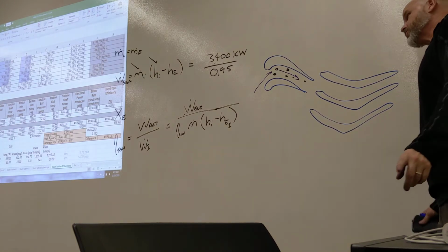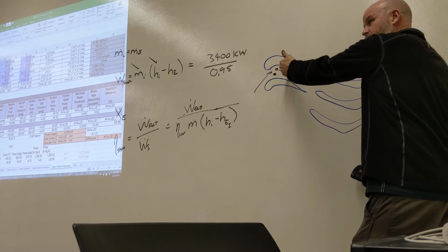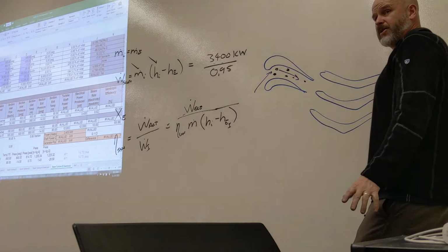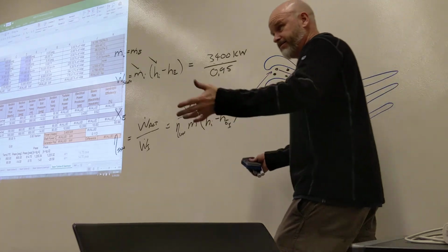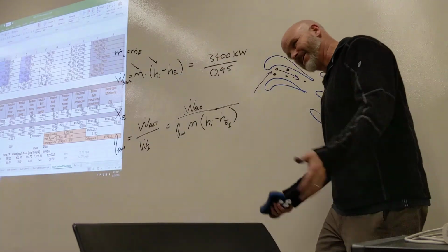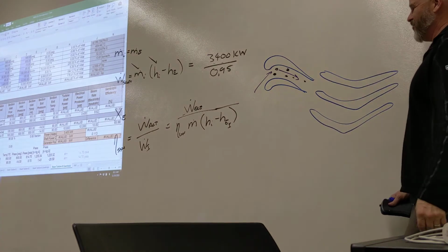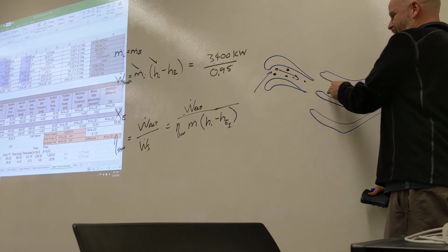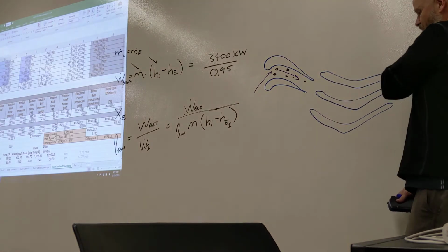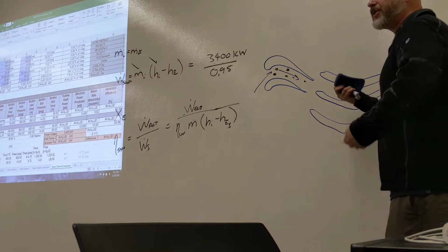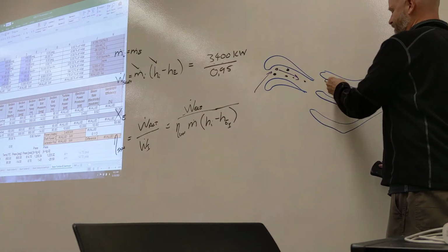So these droplets are going to come out of this nozzle a whole lot slower than the steam, because they didn't accelerate. It's kind of like you guys, just not going. So the steam comes out at high velocity, hits the blade right where we want it to, does what it's supposed to do. These droplets hit the back side of this blade.